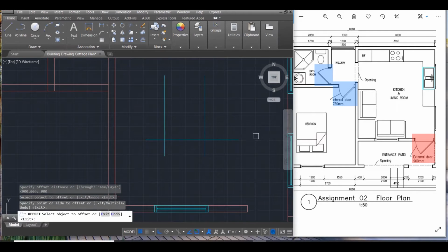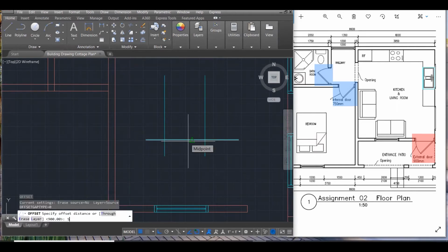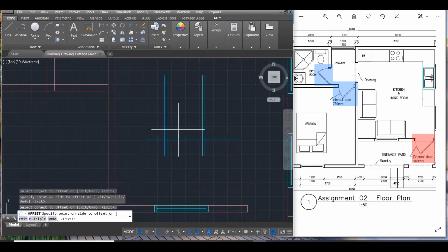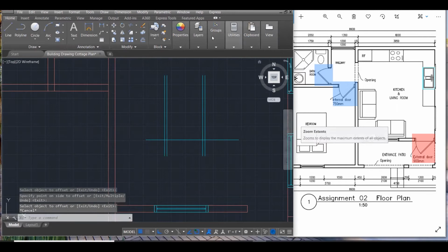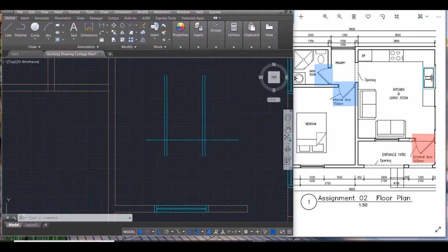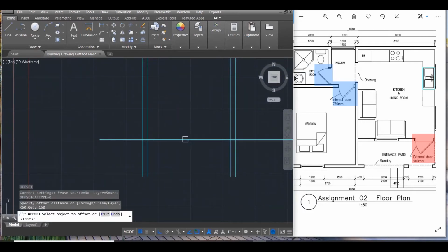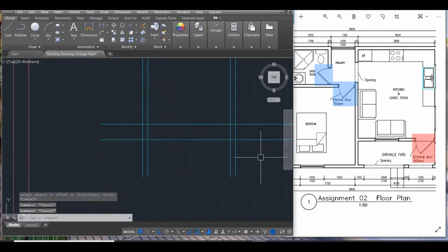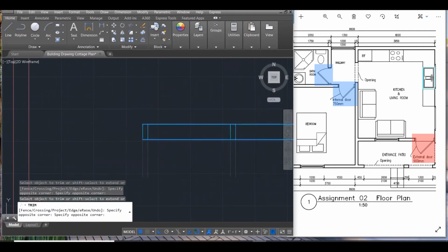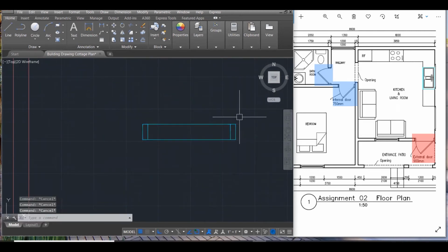Put that in there. And then I'm going to create a frame of 50. Now first, frame of 50 on either side, insert in, and then I need to put in the thickness. The thickness that the door will be, the thickness of the wall is 150 millimeter. So I need to offset that thickness. So I'm going to offset 150 millimeter. Either up or down, it doesn't matter, but I'll go up. Trim this down. Just trim. So this is my frame.